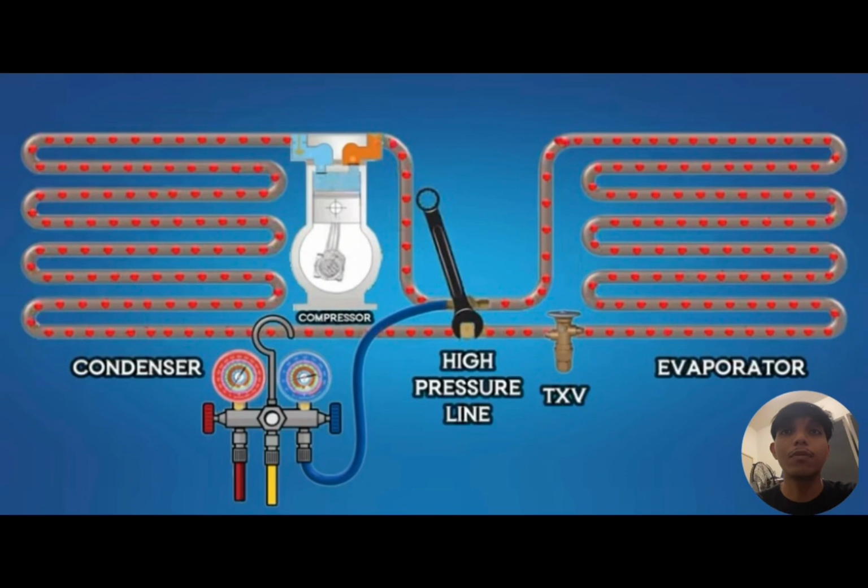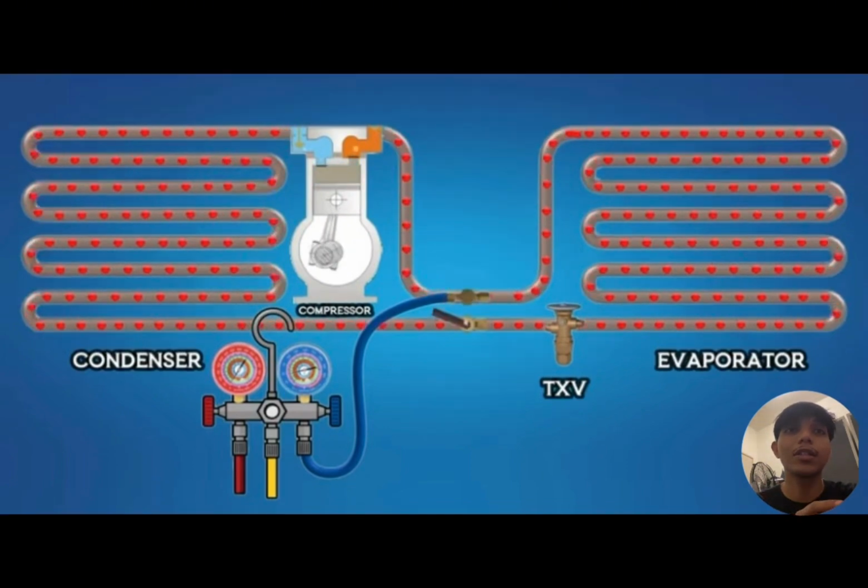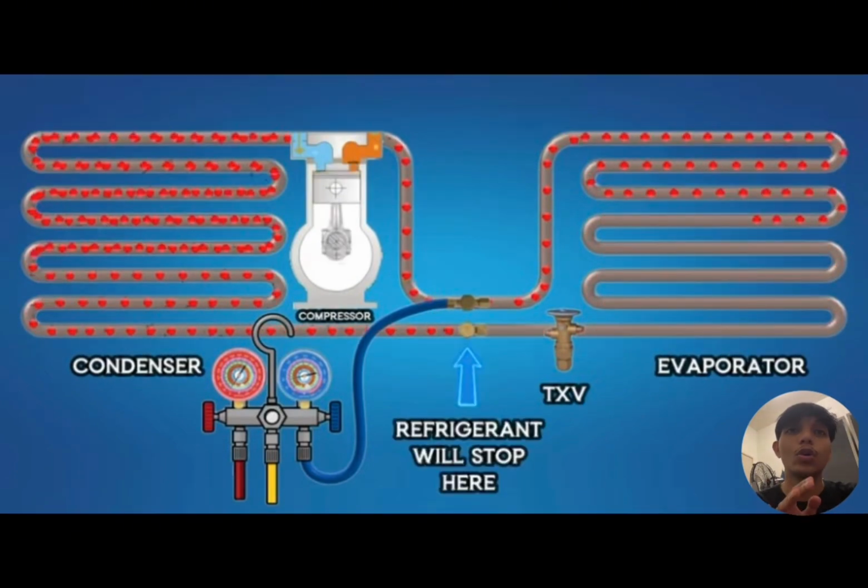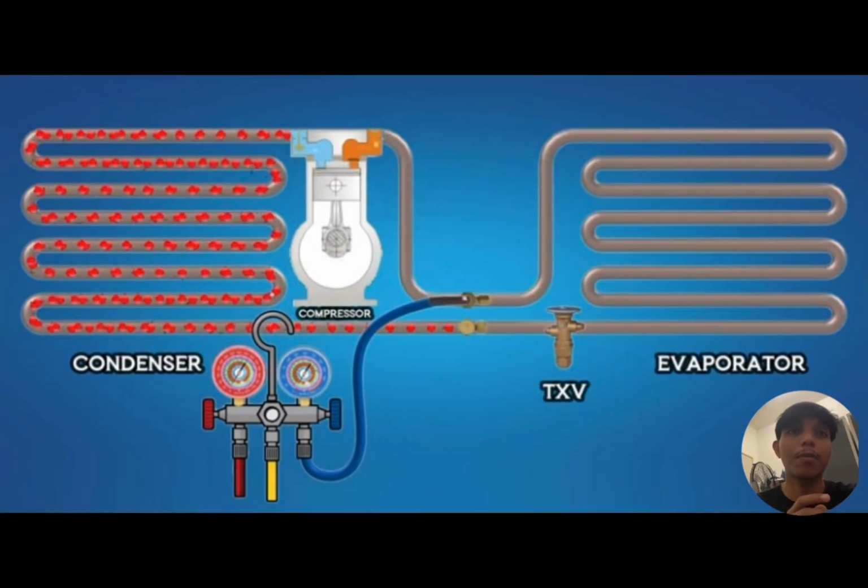Open the valve cap of the service valve on the high pressure side using a wrench. Use an Allen key to turn the valve stem and close it. We can check it if needed. After closing the valve stem, the refrigerant will stop flowing from the outdoor unit to the evaporator. Now the refrigerant in the evaporator and coil will start flowing back to the outdoor unit via the suction line. As all the refrigerant from the indoor unit gets stored in the outdoor unit, the pressure in the suction line will gradually drop.